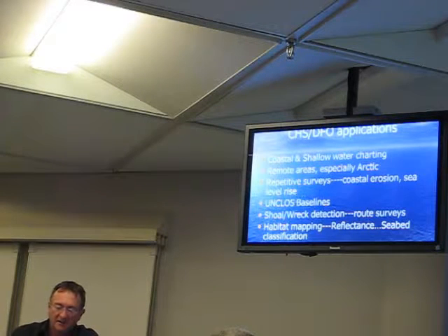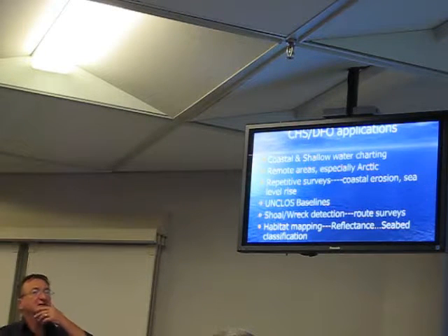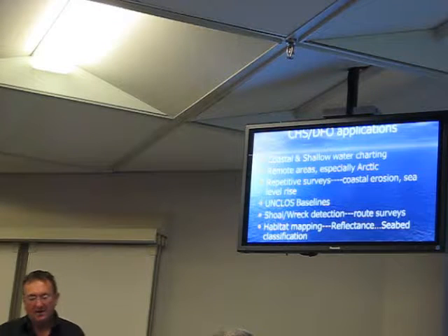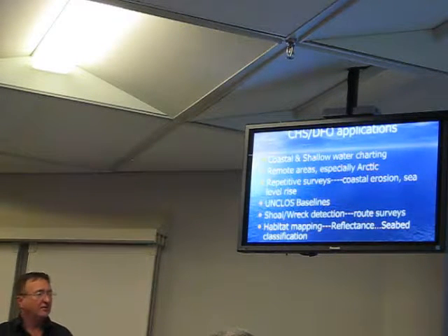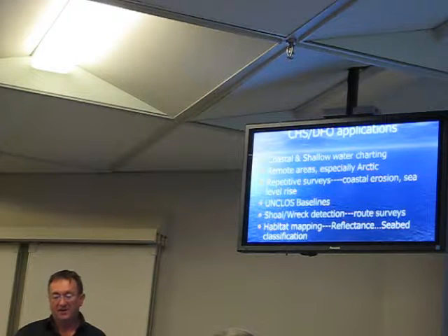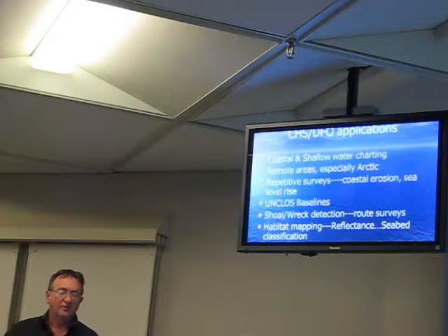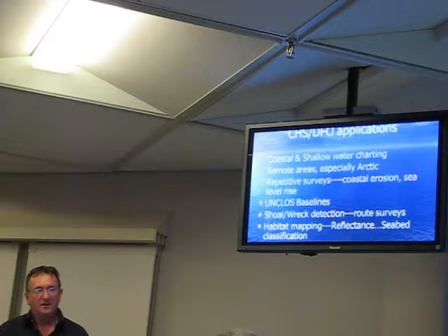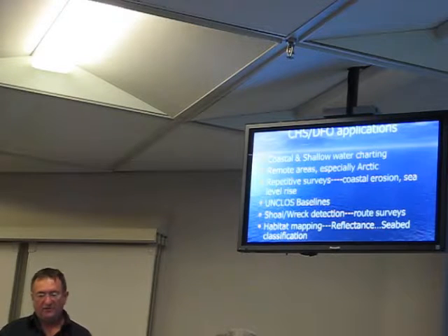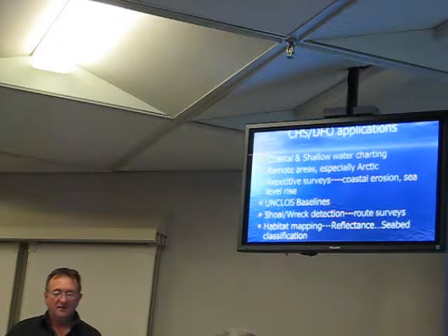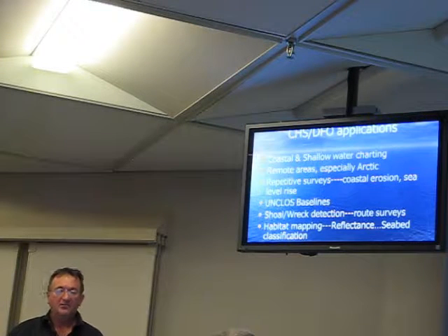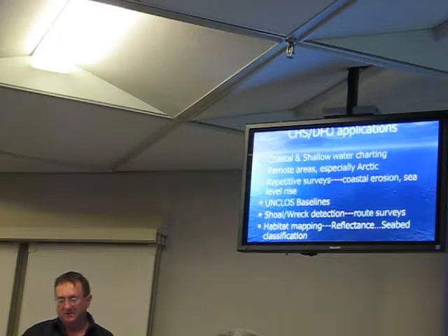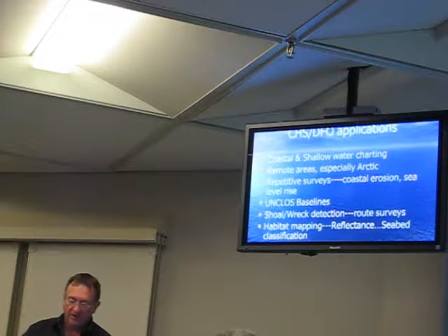also for us. Law of the sea baselines. The basis for all of our offshore boundaries is our baselines, and they're defined as either the low water line on the larger scale national chart, or in the case of where there's open bays and harbors, you pick a series of points at the furthest extent of your shore, which means detecting and measuring any offlying drying rocks is very important to delimiting offshore boundaries.